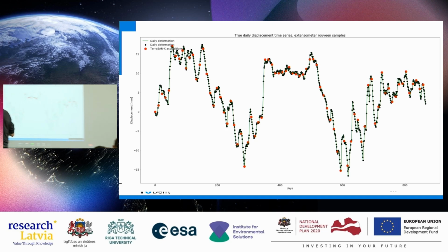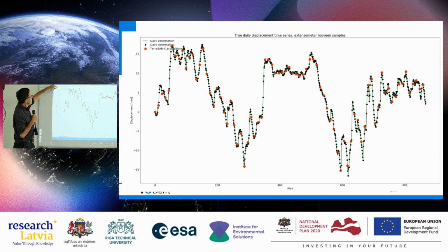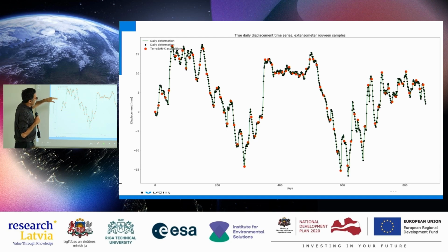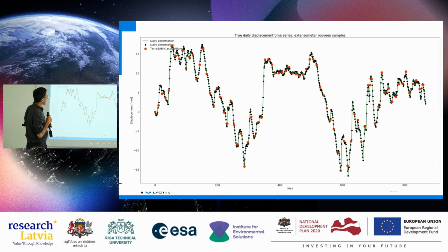And actually it's extremely interesting, because if you look at the vertical scale, it goes up to maybe 17 millimeters up, and maybe also 70 millimeters down. So here we have, let's say, 3.5 centimeters of variation over the seasons. Here is days on the horizontal axis, so here we have a bit more than 2 years in terms of days. And basically what you see is that this is winter time. This peaks over here, then the elevation of the soil is actually quite high. And in summertime, the ground dries out.